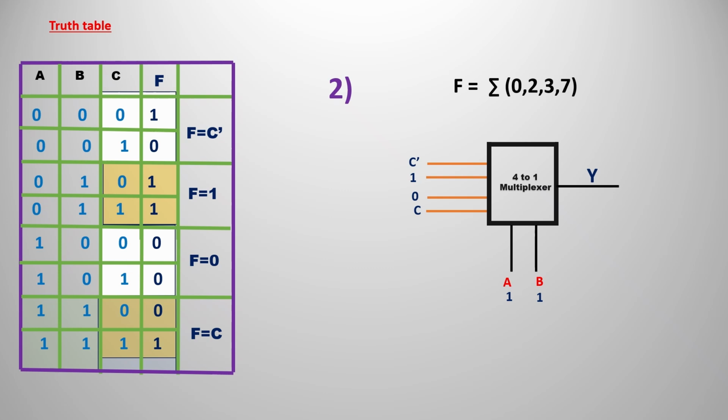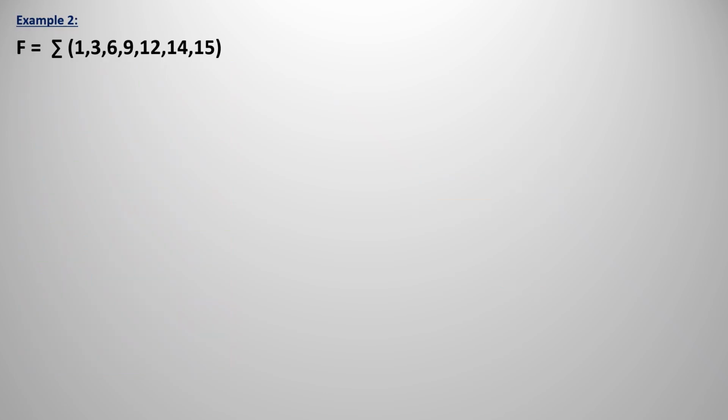So remember these cases, we are going to apply all of them while implementing the logic gates with the help of the 2x1 multiplexer. This is the important concept, that is the second method. Remember this only. The first method is not that many steps, but this is the efficient method, because only n-1 select lines are required for these situations. I hope you understood the concept behind that.